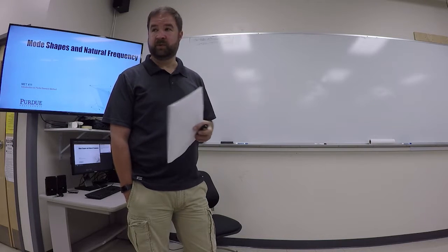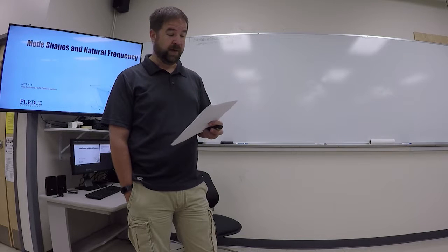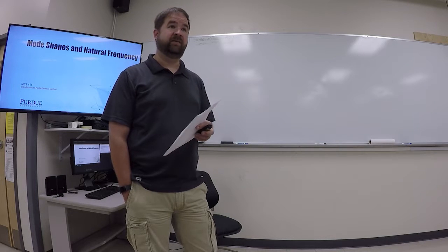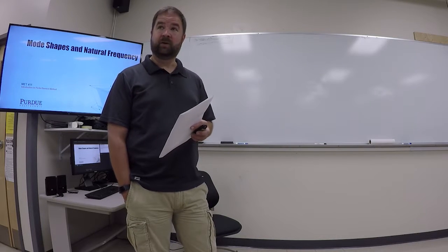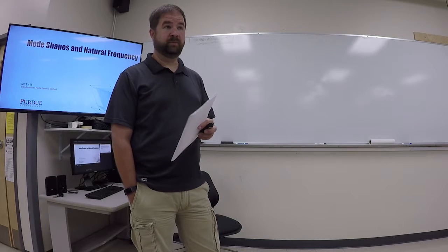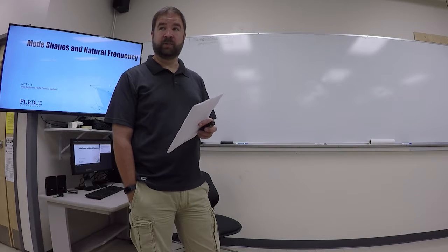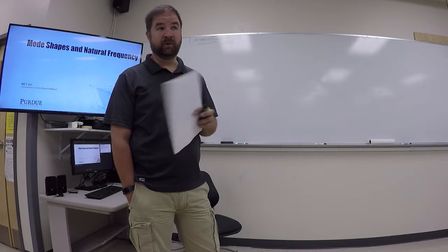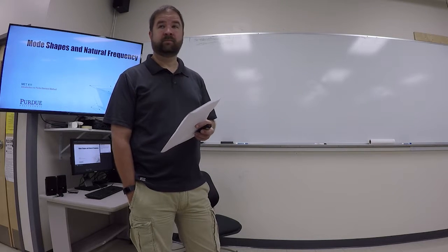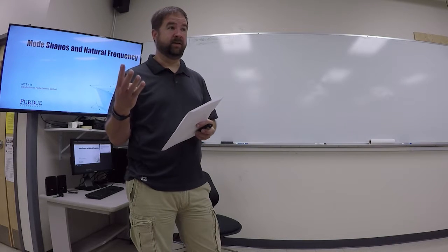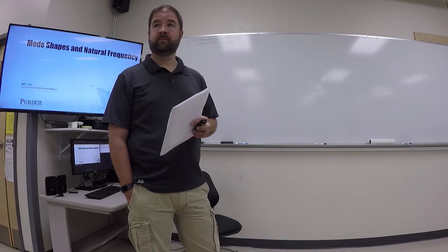That's why I'm going through this whole explanation, so you understand a little bit. Because when you do problem number 2, if you say, give me the first 5 natural frequencies, it will give you the first 5, which will all be 0, and all related to rigid body motion. So in SolidWorks, what do I need to ask for? Modes number 7 through 11, for the first 5.